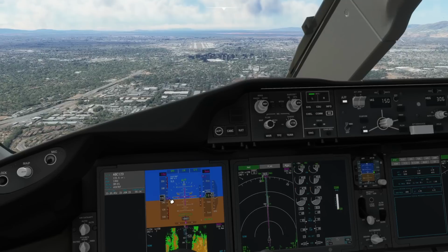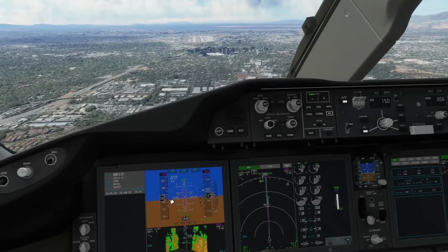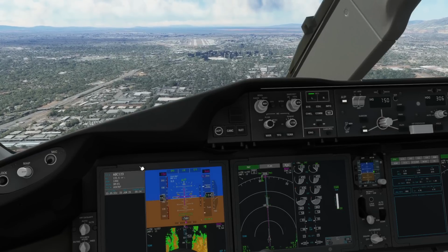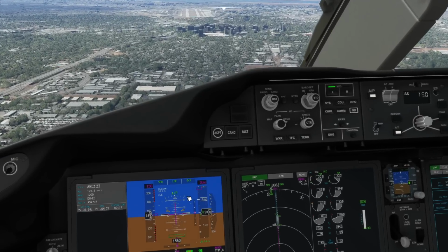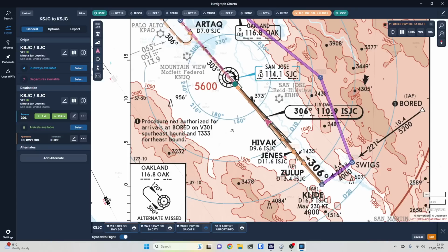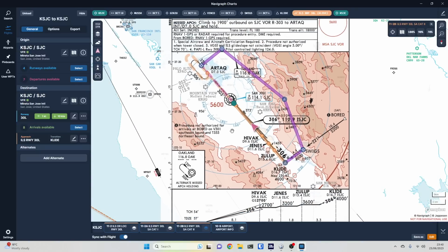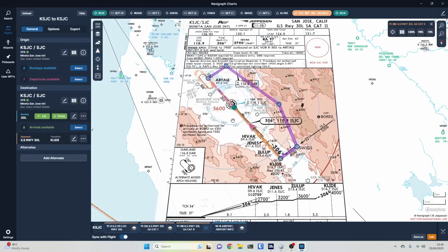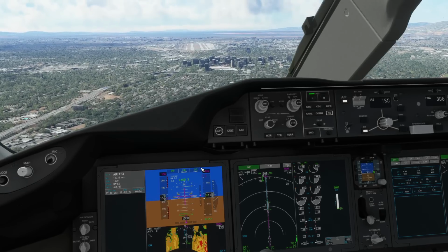So we're at 150 knots, so we're right on the money basically. So it'd be interesting to see if this changes to flare mode. I haven't actually checked... what does it say here? What sort of ILS is it? Can it do Cat 3? No, it's only Cat 2. So we're not going to be able to do... although it has gone to flare.